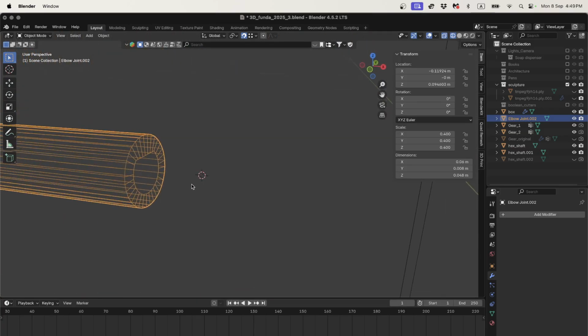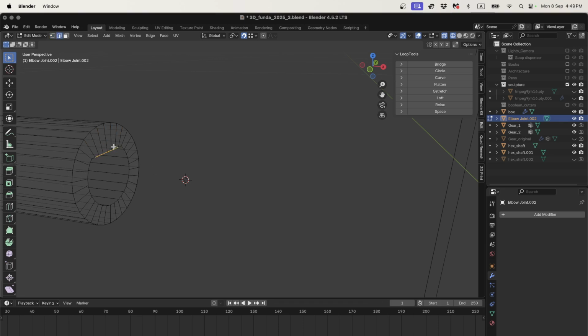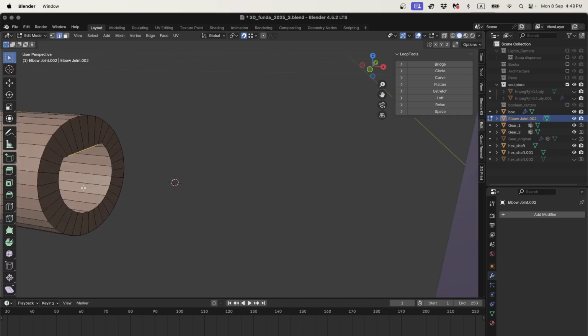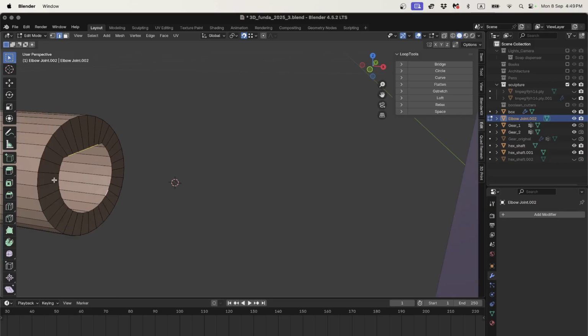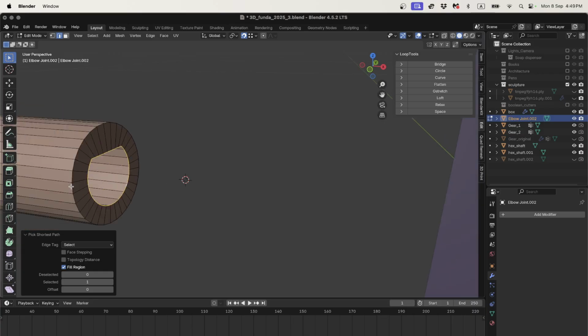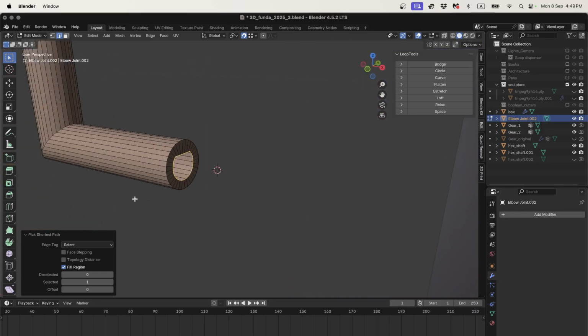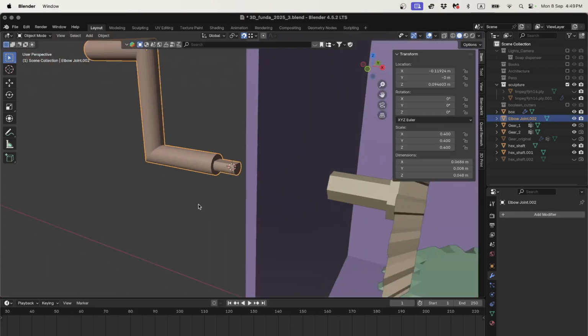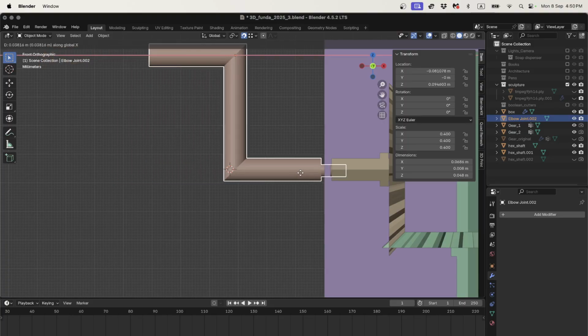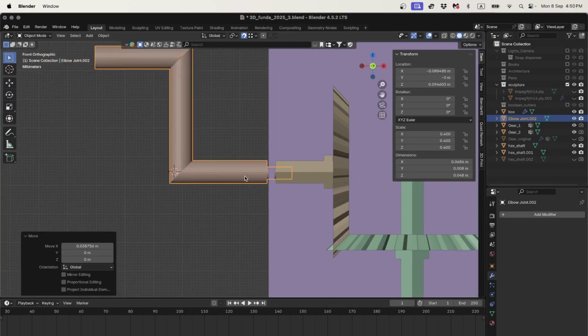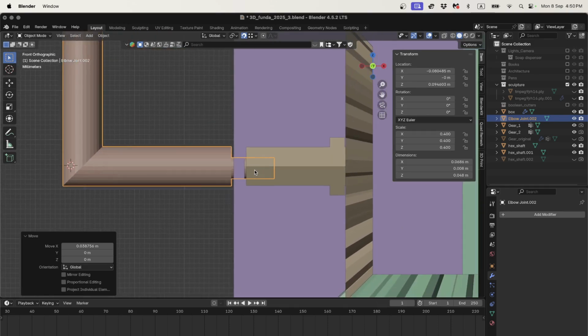And now if I go into edit mode, I'll just go back and get that whole edge loop again. Shift Command left click. It's not letting me get it. That's annoying. Okay, looks like I'll have to get it in a few clicks. Okay, that's good. Because what I want to do is I want to fill this hole, F for fill, and then I want to E and just extrude that pin out. And now we'll just move this into position, GX, and we'll have to work out how deep to make that pin.